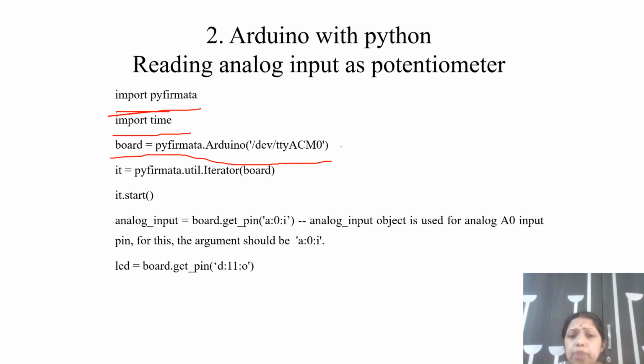Okay, so this is mainly to connect any COM port, any kind of port, with a USB cable between your hardware component and the desktop. Then you can find in the Arduino IDE what the COM port name is. This you have to enter here only. The COM port name is different for Linux and Windows, right?